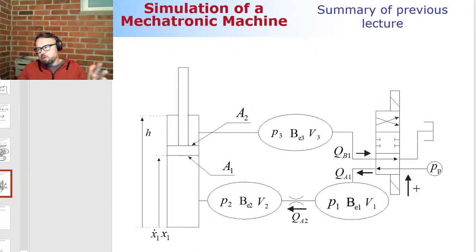Let's look at a little bit more realistic hydraulic circuit. Here is an example we looked at previously. Here, we're computing the pressure in this pipeline, and this could be, in practical life, a longer pipeline. If that's the case, then we're simply making an assumption that the pipeline is not introducing significant pressure losses. That may not be exactly according to reality, but it's the best guess we can make. Also, because we have just the one pressure, we cannot take the pressure fluctuation because of the pressure waves into account. That's the thing we're ignoring when using the lumped fluid theory.